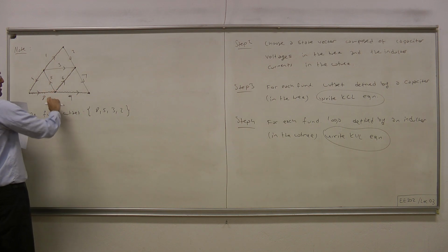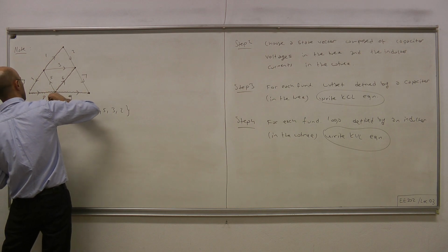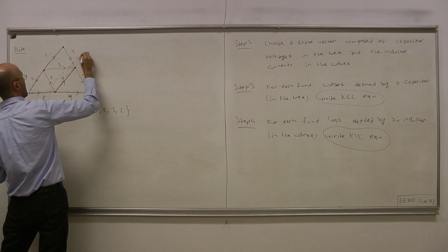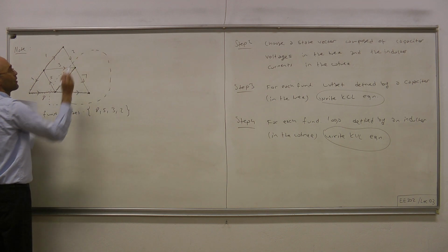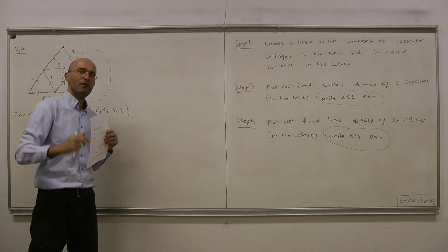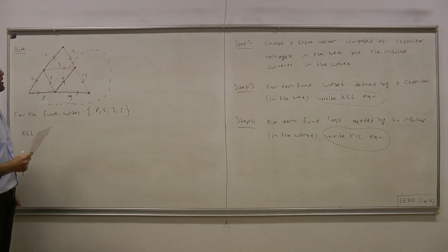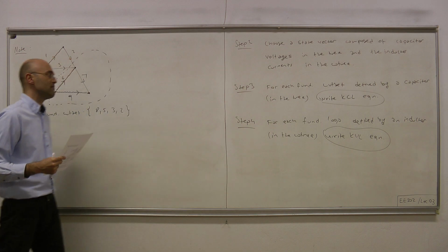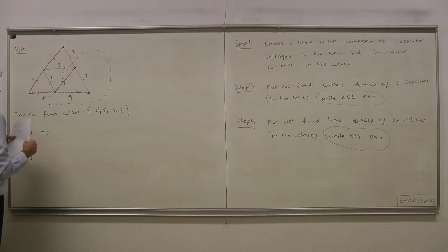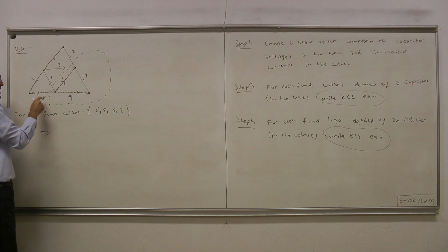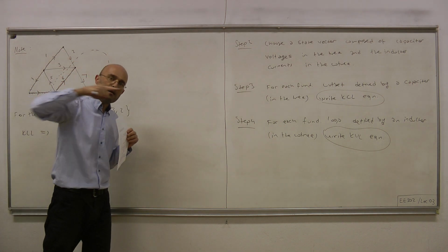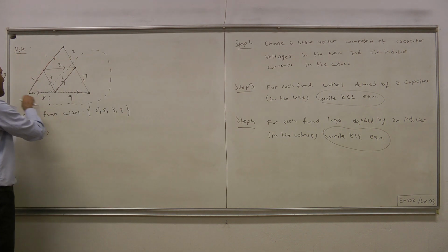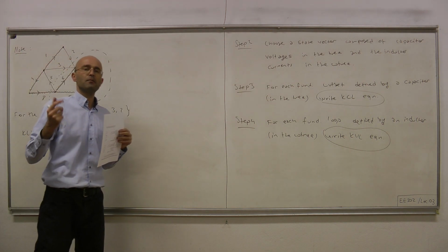Now, we can consider this cutset as a closed surface, and therefore by KCL we know that the sum of currents entering a closed surface must equal the sum of currents leaving. Now we have this 8, suppose it's entering into our closed surface, and suppose everything else is also entering. So all the currents are entering, and then the sum of all those currents must equal 0.